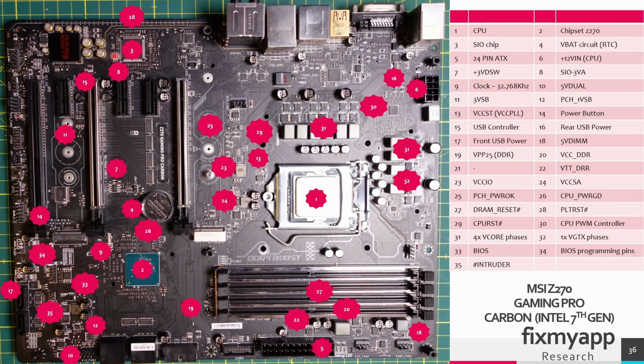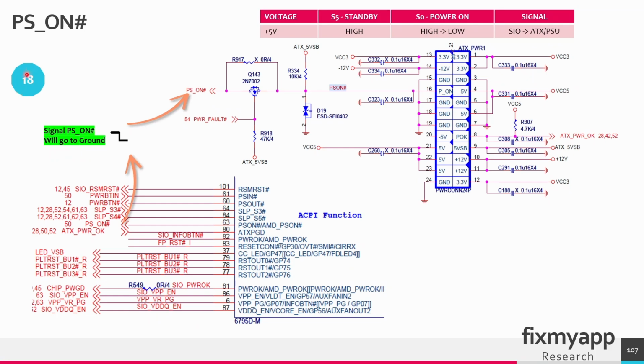The power supply on signal can be found near the Super I/O chip, and this signal will be sent to the 24-pin ATX power connector. From this connector, the signal goes to the ATX power supply. In power sequence 18, the Super I/O receives the two sleep states, S3 and S4. When the Super I/O chip receives those two signals, it will send a signal back to the ATX power supply to turn it on. The signal is called power supply on, active low. When the signal is pulled to ground, it will go to the 24-pin ATX power connector and then to the ATX power supply. Because the signal line is pulled to ground, the power supply will activate or turn on all those voltages.